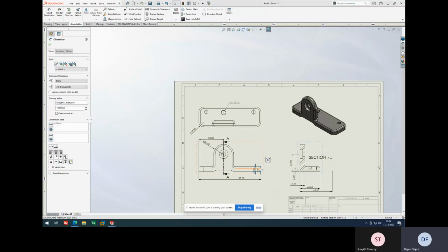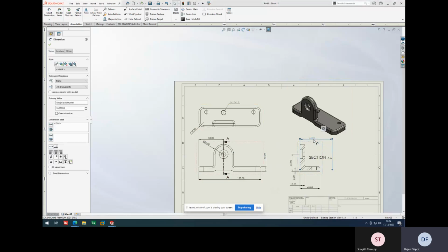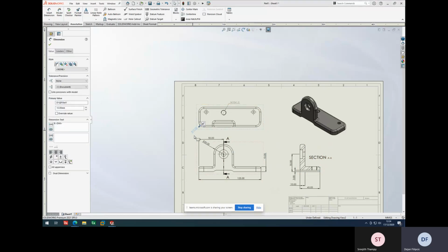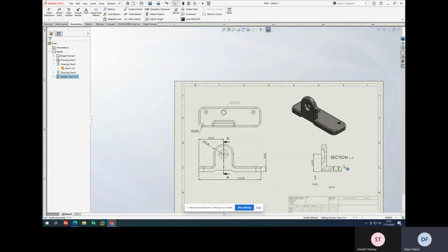That's where you save a lot of time. Out of the entire drawing, the only dimension he made manually was for that threaded hole, because it wasn't there before. All the other dimensions were already there. That's why it's so important, when you do dimensioning of a sketch, the type of modeling, and the sequencing, that if you put a bit more effort into how you do your 3D, you can pretty much do your drawing automatically. And that's the beauty of these softwares.